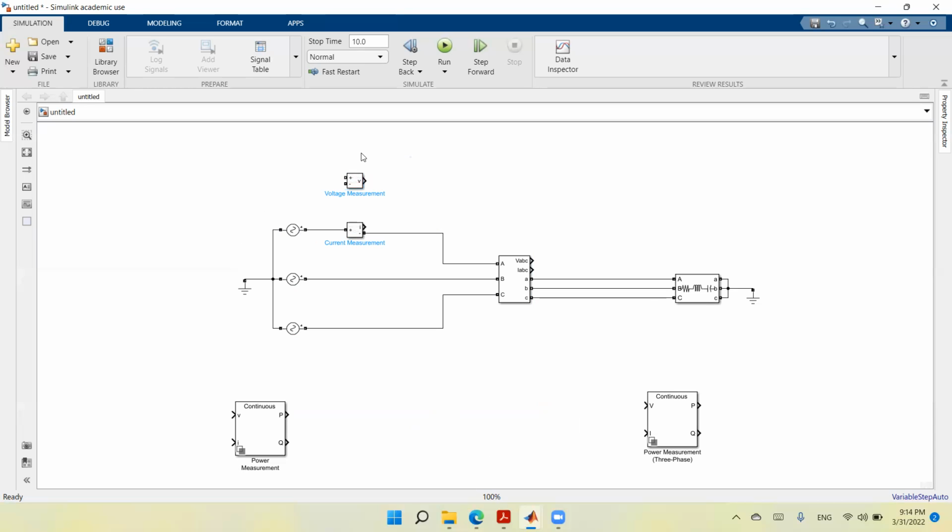All these names represent one voltage. So the positive terminal will be connected to one of the lines. It could be phase A, B, or C. And the other terminal should be connected to the neutral point. But since the neutral point is grounded, I can connect it to the ground.